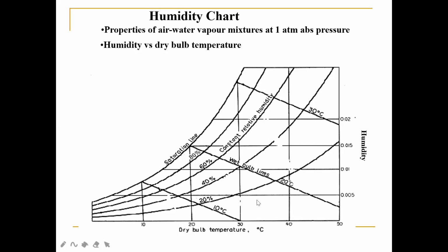Okay, for you to be able to do the calculation and also to design the cooling tower, you will be using a humidity chart, and you have to be good in reading your humidity chart. I think from the last batches of seniors previously, they all told me that you have been taught on how to read a humidity chart, right?